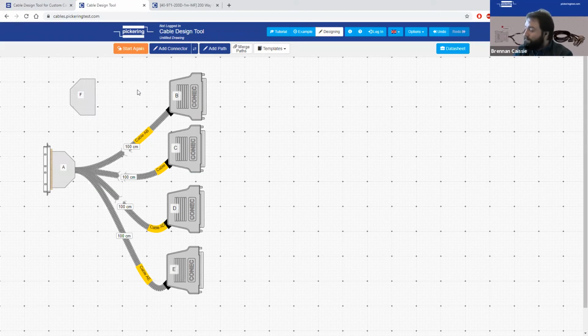Yeah, I believe Brendan added that if it's unterminated, in other words, a connector on one side and unterminated wires, you can indicate on those what exactly the signal type is. So you can put markings in, but not when the cable's bundled together like this. Yes, in the case of unterminated, the unterminated ends can be labeled.